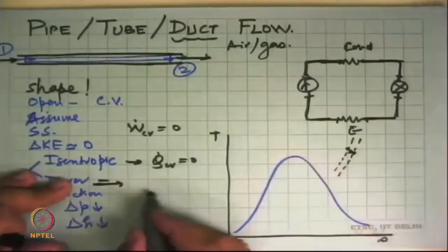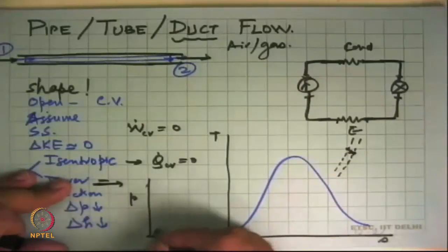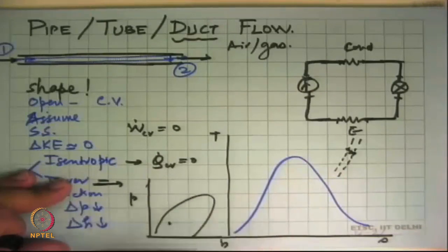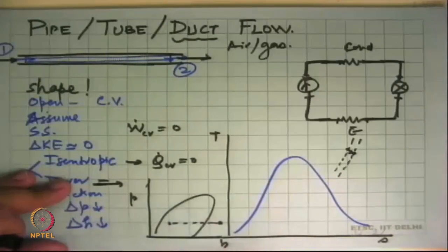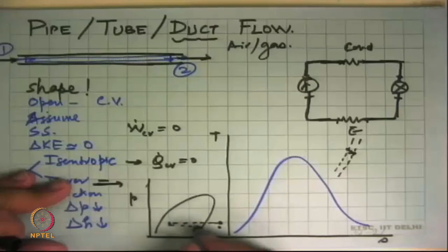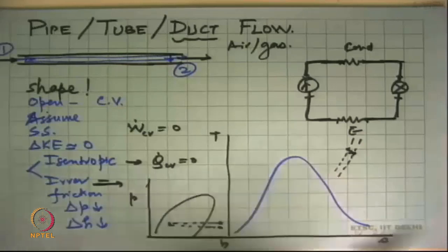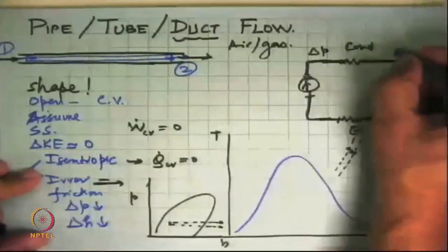That's what would happen in a real pipe. On the PS diagram, when we have the dome there, we say that okay, we are pumping it through the evaporator from here to there. Ideally, we assume it to be a constant pressure process. Practically, the pressure will be slightly less, and so the process will actually be something over there. So in practical design of these types of systems, we will take care of pressure drop in every one of these pipes.